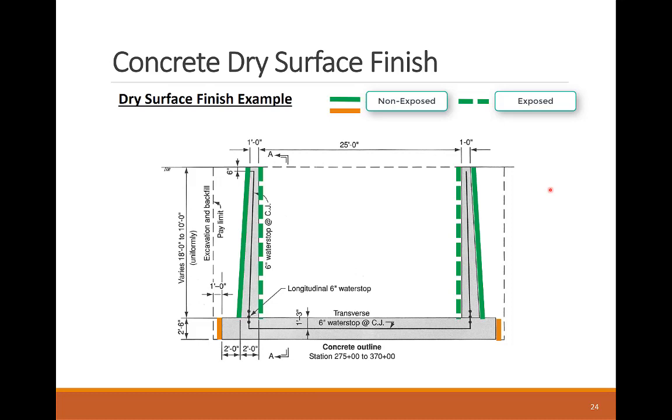For the example structure, the outside dry faces after removing the formwork require non-exposed treatment, as they will be covered after the soil around the structure is backfilled. The inside faces of the walls will require a higher level of treatment, as it is considered an exposed dry surface.